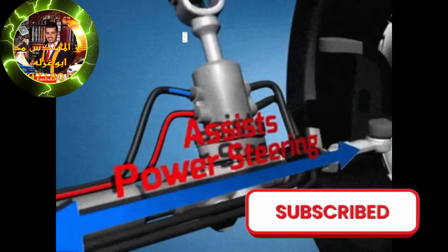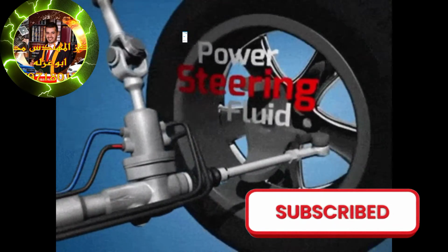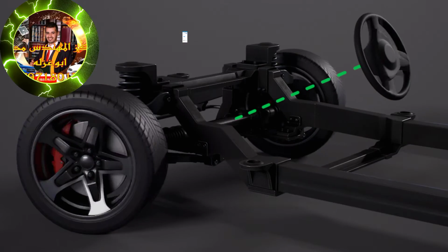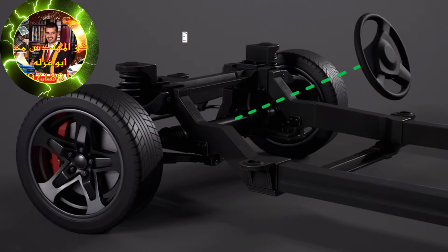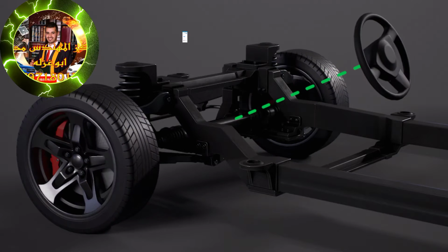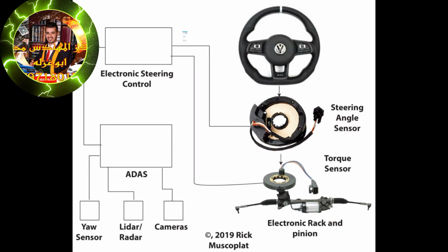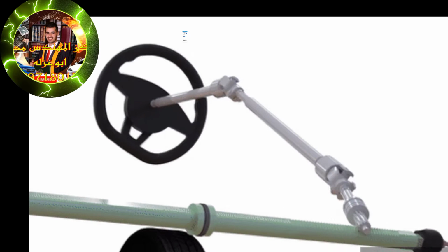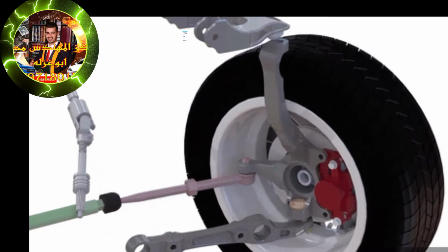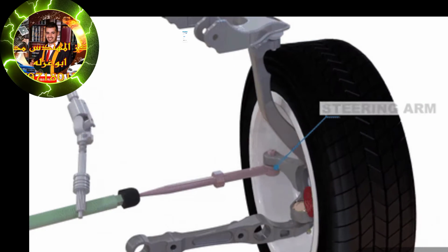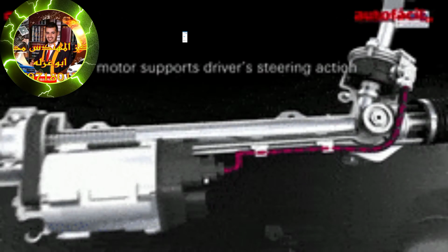4. Steering linkage. The steering linkage consists of various rods, joints, and components that connect the steering gearbox or rack to the wheels. The steering linkage transmits the motion from the gearbox, rack to the wheels, allowing them to turn. 5. Pitman arm, center link. In a traditional parallelogram steering linkage, a pitman arm connects the steering gearbox or rack to the center link. The center link, also known as the drag link, extends horizontally across the front of the vehicle and connects to the steering knuckles.